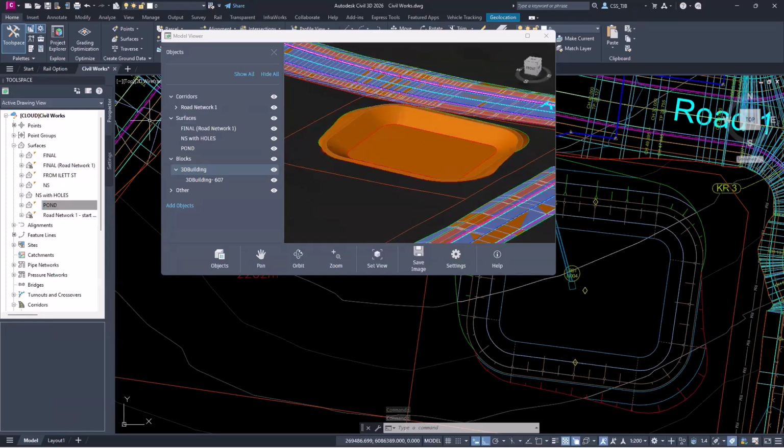All right. Todd, sorry, just a quick question. I think we've sort of answered this already, but the question was, could we drape the lot numbers to a surface? No, not easily, because they're 2D objects. You'd have to assign the elevations.